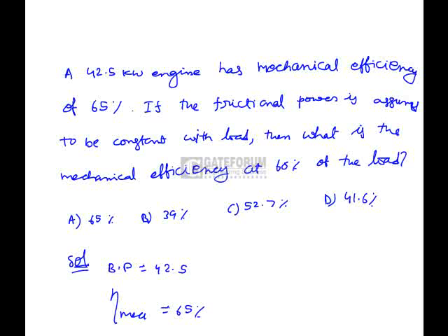This is the indicated power of the engine, but here we will have to find out the mechanical efficiency at 60% of the load. So at 60% of the load, the brake power required is equal to 0.6 into 42.5, which is equal to 25.5 kilowatts.